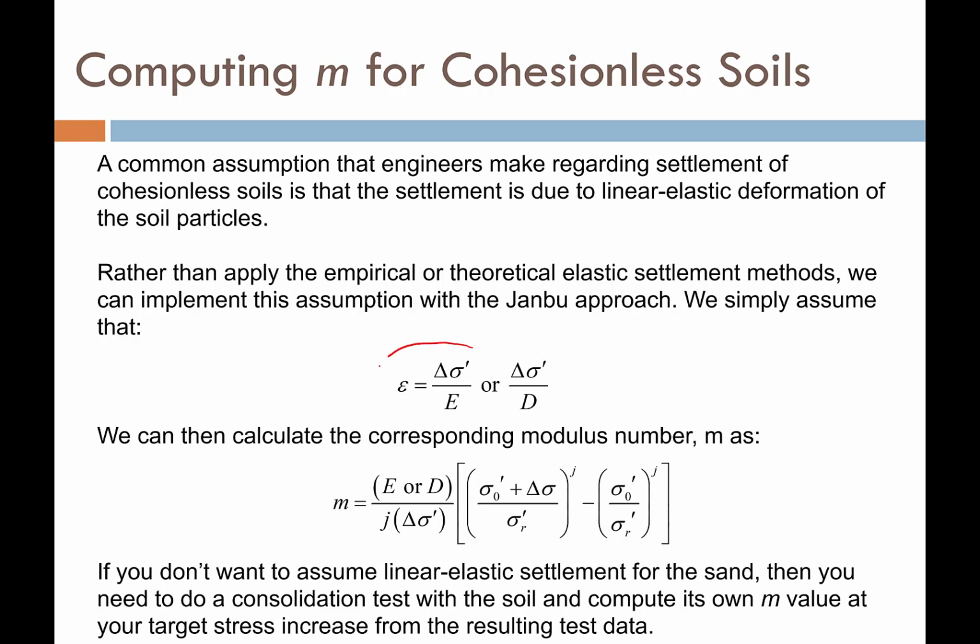So we're just going to use this basic assumption where the strain is equal to the change in effective stress, this is my induced stress that I can get from elastic induced stress methods, or I can get from finite element, divided by E, which is my Young's modulus.